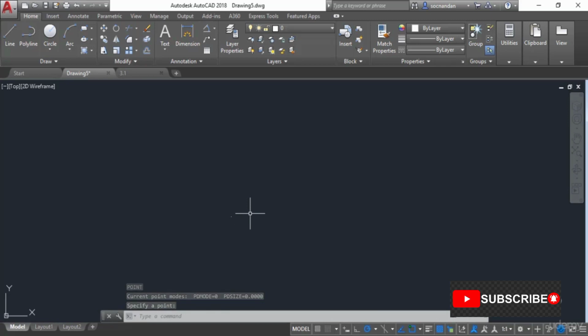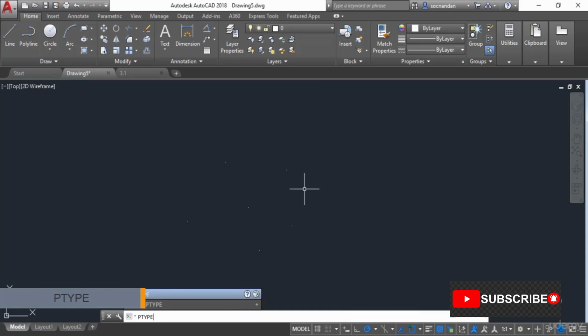Now in order to make another point, simply press enter or spacebar to repeat the last command and click again. And you can repeat this process a couple of times to make multiple points here in the drawing area. So now we have a couple of points here in this drawing area, but the points are very small, almost of the size of a single pixel and they are not clearly visible. In order to make them visible, you can change their style or their type, and you can change that using the PTYPE command. So let's type PTYPE on command line and press enter.